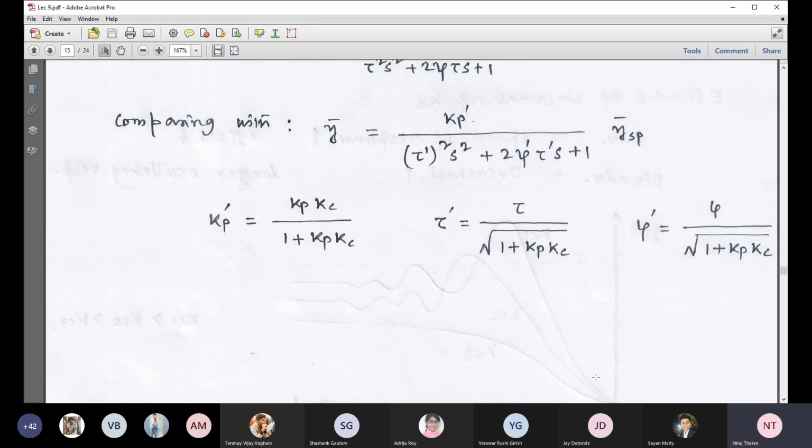So the comments are the same, you know. Kp is greater than Kp prime. Second order process plus P only is equal to a second order process. There is no change of order, you see. We started with a second order process and we end with a second order process. So our first remark is that there is no change of order.